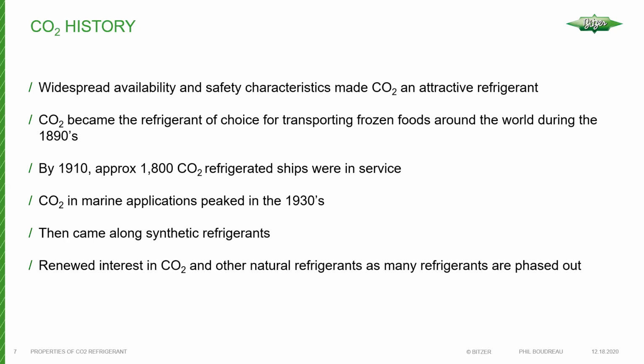And then, as you know, in the 1930s came along the synthetic refrigerants. So some of the earlier ones, such as the R12 and 500, and I guess at some point 502, and later on around World War II was R22. These are all synthetic refrigerants. And then over time, we learned that there were issues with these refrigerants, right? So we had the ozone depletion, and now more attention is being placed on the global warming potential side of it.